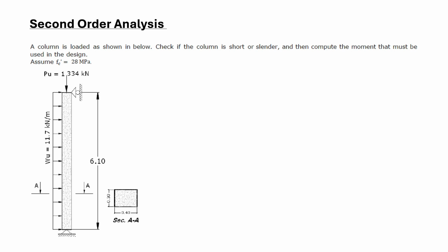Today we will use second-order analysis to account for the effects of deformation on the structural behavior of a system. Long columns can exhibit nonlinear behavior under load, especially when they are close to their buckling limit. Second-order analysis incorporates these nonlinearities, providing a more realistic picture of how the column will behave under various load conditions. Also, at the end of this example, we will compare the results with that obtained from ETABS.